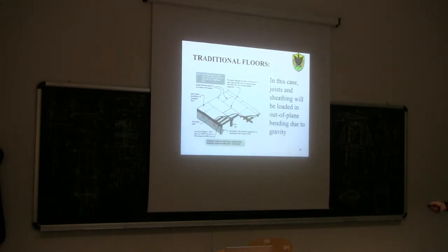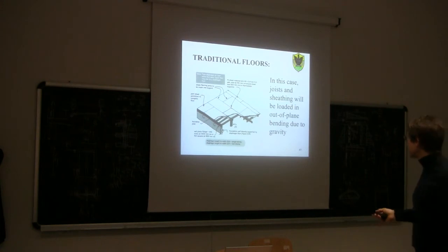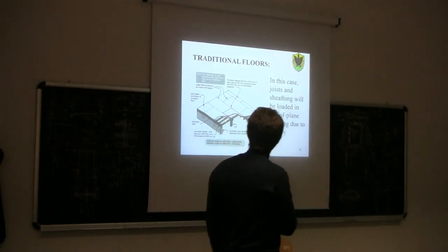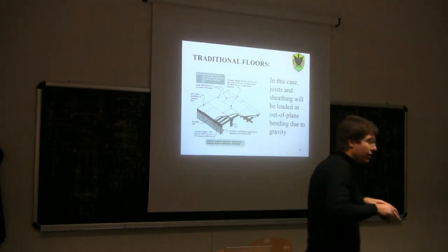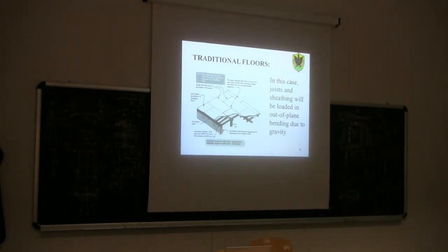It's very important that the sheathing panels are alternated in this way you can see here. The joint between two adjacent sheathing panels is a discontinuity joint. Of course, then we can get the continuity of the forces by nailing. It's a good rule, it's actually mandatory, that those sheathing panels are staggered, so that the joints are not on the same line. Okay, so they must be staggered in this direction, as you can see here.